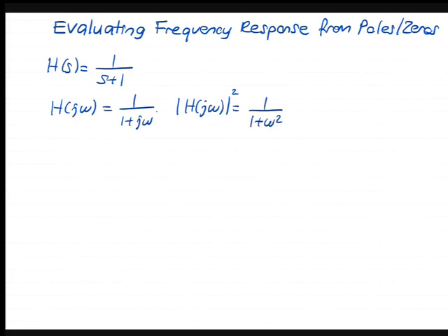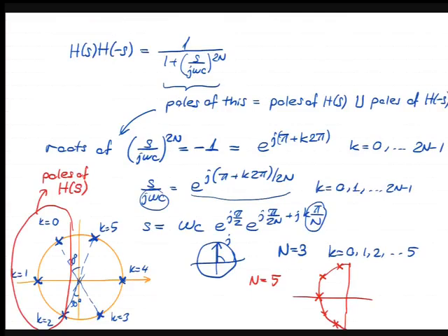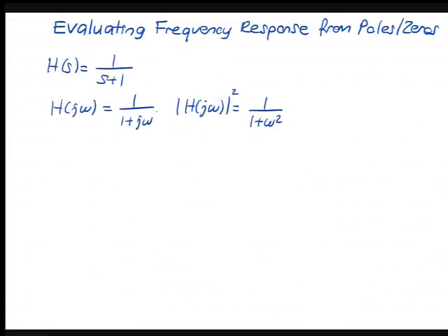It's a bell-shaped thing. Not too different, in fact. That's actually a Butterworth filter of order 1, right? Because if you go back to this, n equal to 1 means you have only one pole. And that's going to be negative and real at negative omega c, right? So that's the simplest, cheapest low-pass filter you can design. But looking at the poles, how can I tell this is a low-pass filter? So one way to do that is to make a pole zero plot in the complex plane.